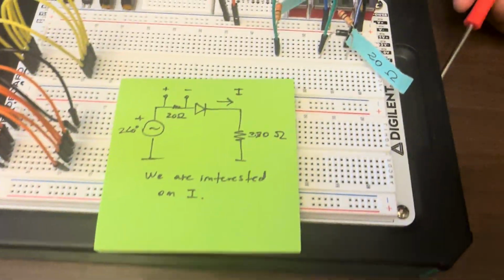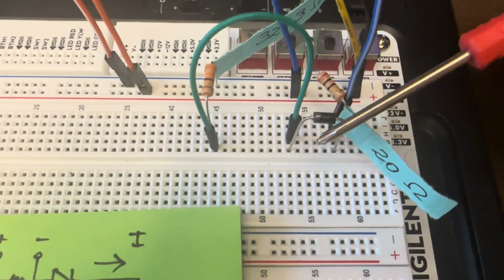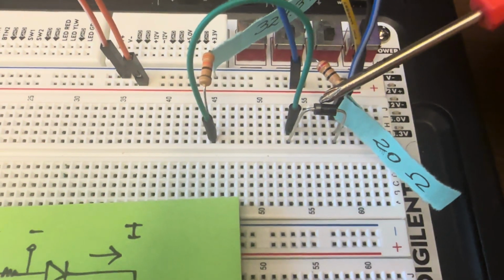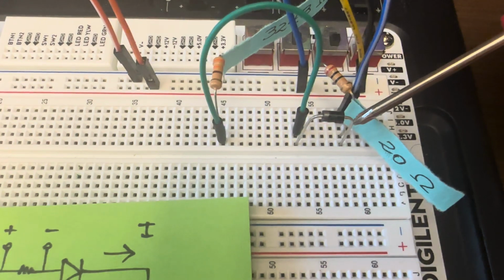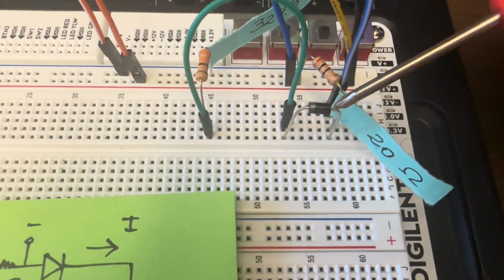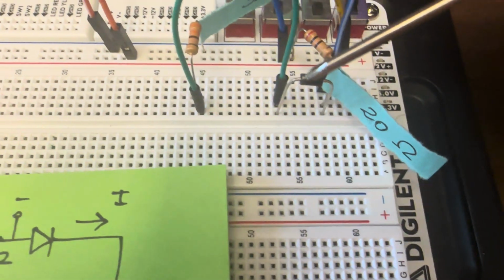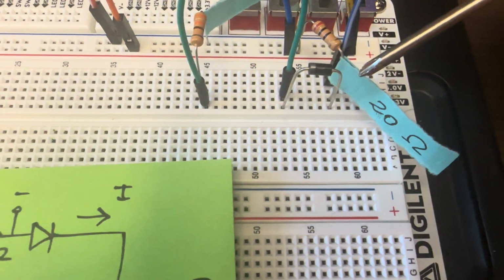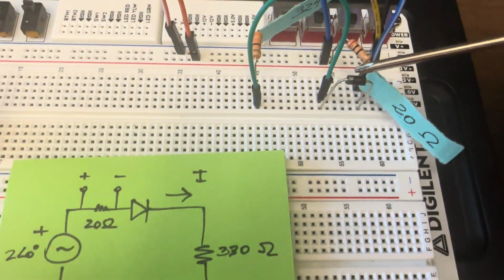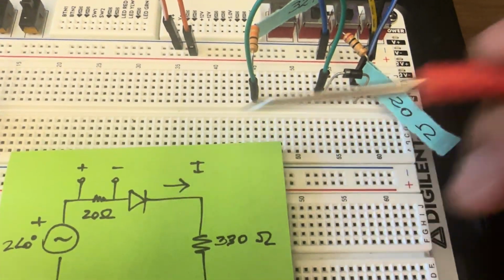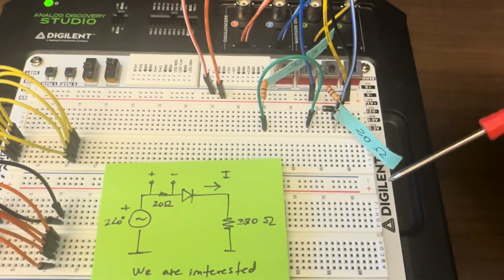I hope you're familiar with this circuit, and one small recommendation is to make sure about the polarity of the diode, it's always like this, right? So it enters through the negative of the diode and goes out through the positive, the marked terminal of the diode. That's a way to identify how to implement this. So basically this terminal corresponds to the marked terminal here. That's what we're doing. I hope the implementation is clear.